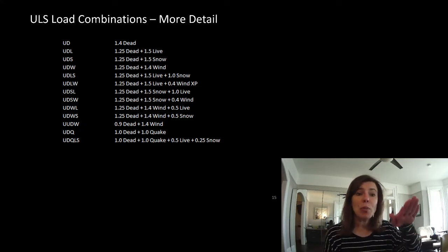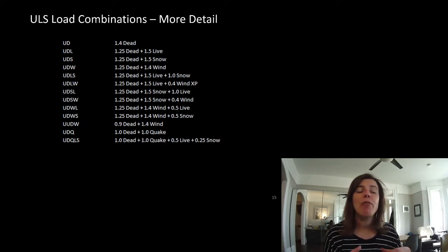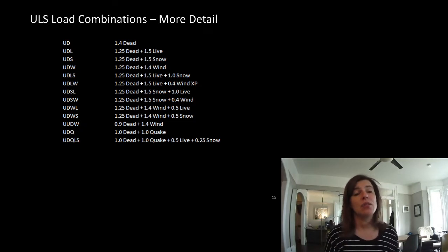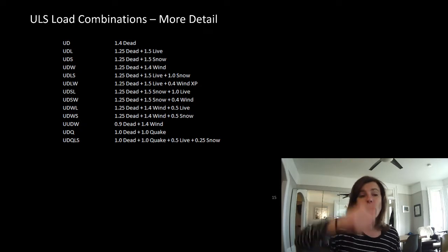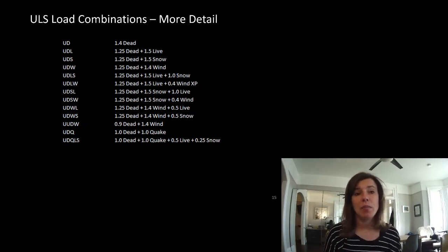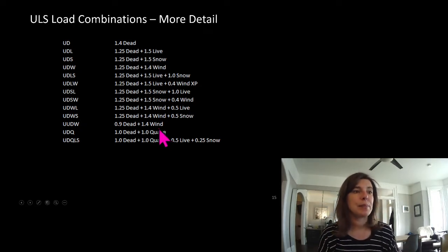If we multiplied that dead load by 1.25, we're saying we have more dead load than we thought. And what we're worried about is this umbrella blowing away. So we want to be conservative and say, there's a possibility there's not as much dead load there as we thought. So let's assume it could be less than we thought, and then factor the wind load pulling it up, so that we're comparing those two things.